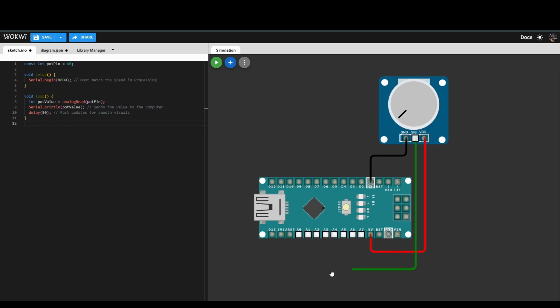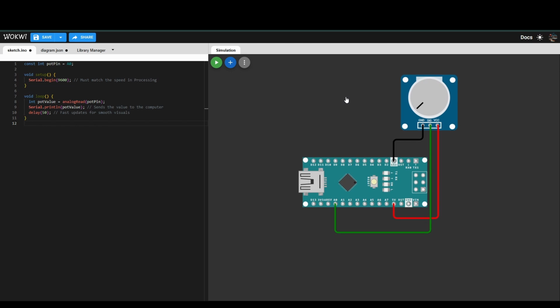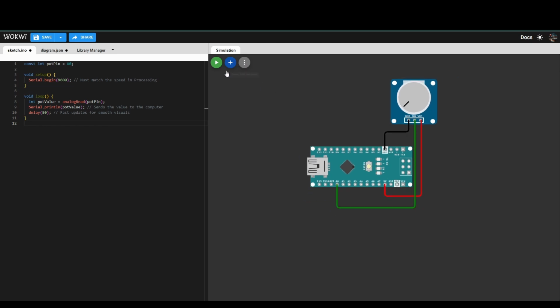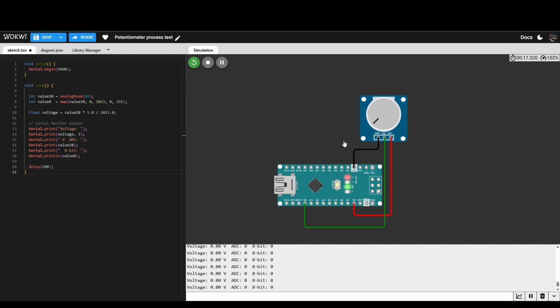At the end of this project, it demonstrates how an Arduino Nano can easily convert an analog voltage into digital data using its built-in analog-to-digital converter, ADC. The data is then sent to a processing application, which I created with a software called Processing, which works with the Arduino IDE, where it is displayed as a number, binary value, LEDs and a live graph.